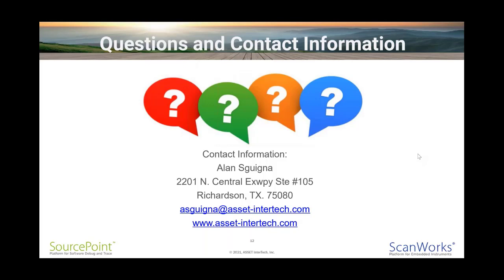Okay, we have two last questions, and they come in back to back. So can you show a dump of memory, presumably via physical address? Yes, I can. We don't have the target live now, but you can do a dump of physical memory, for example, via the memory window, if you're using the interactive, visual aspects of SourcePoint, and suffix it with, for example, the P instead of the L, if you wish, depending on where you are in the code.